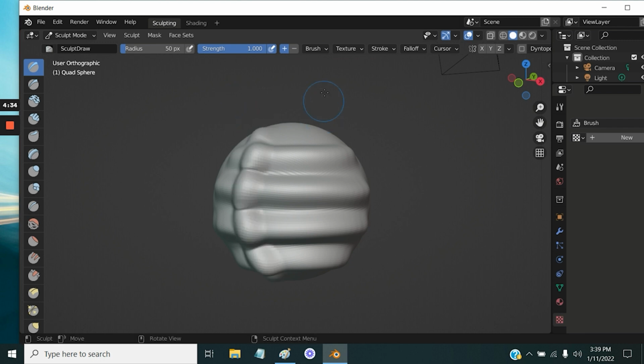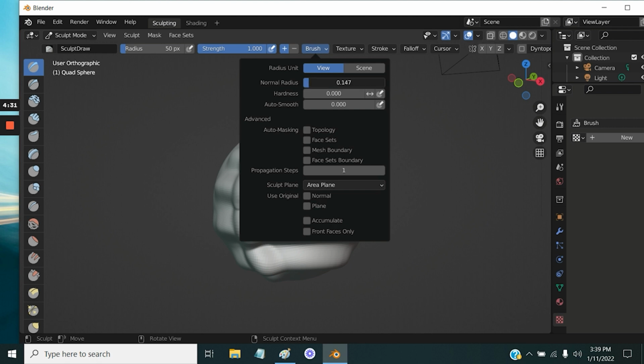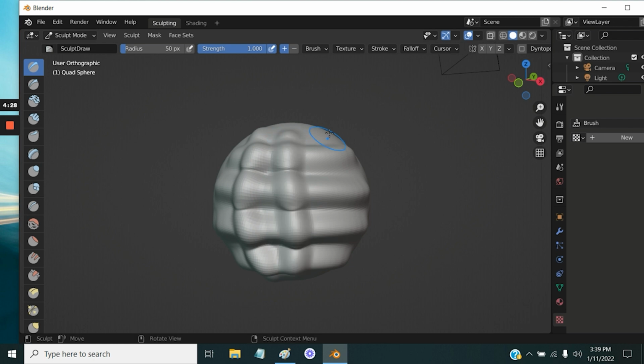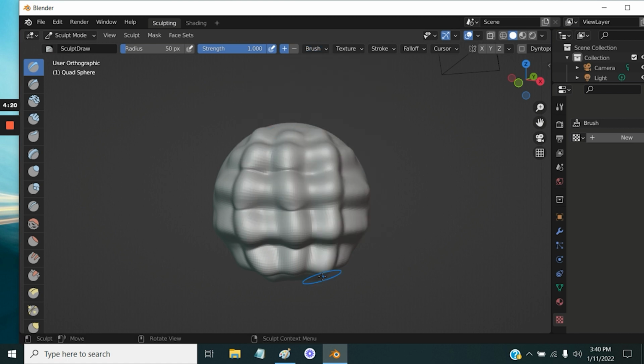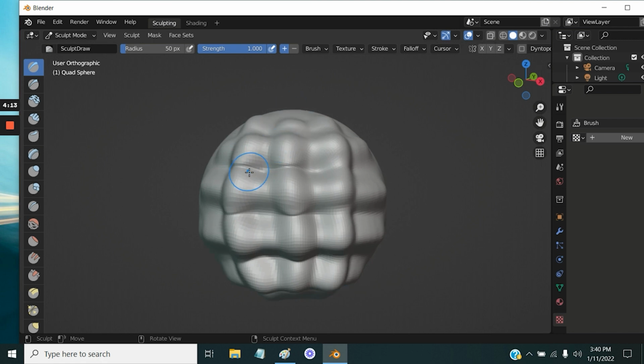draw your line, set it somewhere in the middle, draw your line, and set it somewhere a little higher, and draw your line. So I started this off with a couple lines already drawn, just to show, again, it's about sensitivity. With a lower number, you see the stroke kind of fold over on itself, trying to conform to the bumps that are already there, whereas with a bigger number, the stroke kind of goes right through it. So that's a demonstration of that first option.